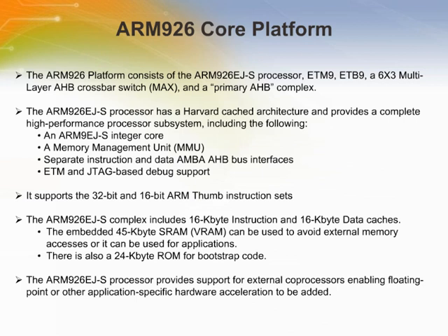The ARM926EJ-S, or the ARM926, is a member of the ARM9 family of general-purpose microprocessors targeted at multitasking applications. The processor is intended to operate at a maximum frequency of 400 MHz in order to support the required multimedia use cases. Furthermore, an enhanced multimedia accelerator and LCD controller are included in the application processor domain to offload from the core functions such as color space conversion, image rotation and scaling, graphics overlay, and pre- and post-processing.